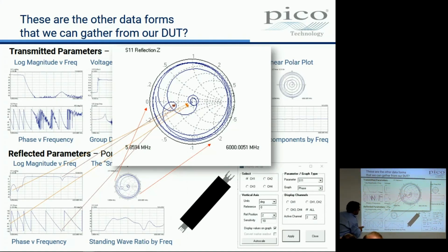And phase increases. So again, look, as we go up in frequency, we go around like this. And then as we come to this point, as we come to the roll-off, look, the reflection starts to get bigger in magnitude. It's still sliding around in phase. So here it is, it spirals out. And it comes to the circle of mismatch. So it started at the point of match, and it spiraled out to the circle of total mismatch. Yeah? And we'll see more about that next time. So that's how those two plots relate to that.